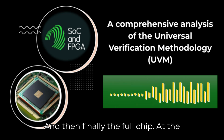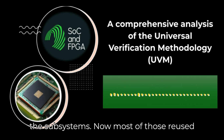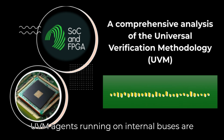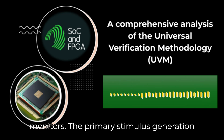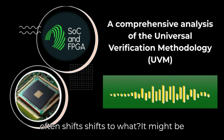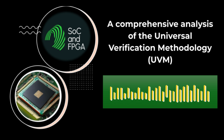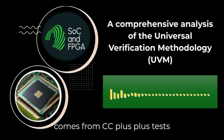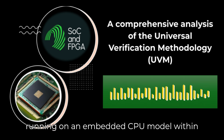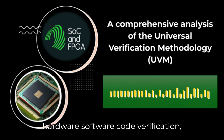Got it. And then finally, the full chip. At the full chip SoC level, you integrate all the subsystems. Now, most of those reused UVM agents running on internal buses are definitely in passive mode, acting as monitors. The primary stimulus generation often shifts. Shifts to what? It might be high-level virtual sequences coordinating system-level scenarios, or increasingly, especially for SoCs with embedded processors, the main stimulus comes from C/C++ tests running on an embedded CPU model within the simulation. For more realistic hardware-software co-verification.